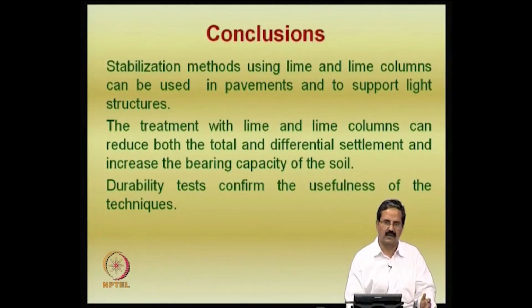You can also measure the in situ swell pressure, like you can take an undisturbed sample, or you can do a lot of tests there. So, the swell pressure should be higher. If it is higher than the loading that is coming, it is a serious problem.